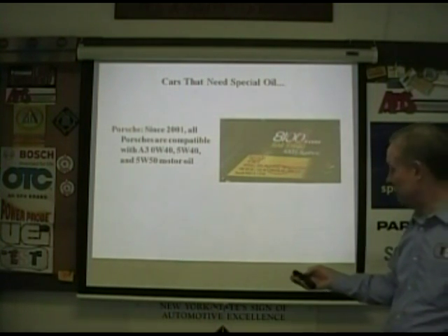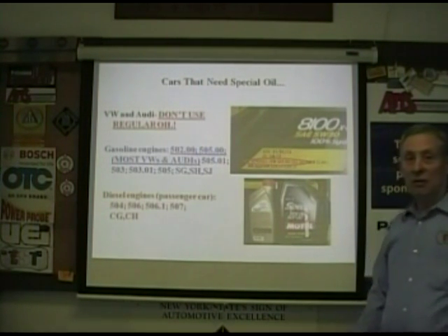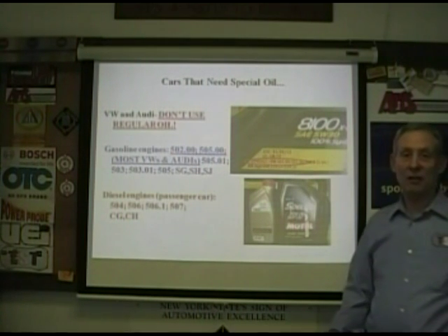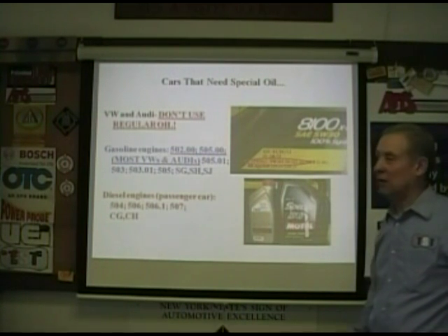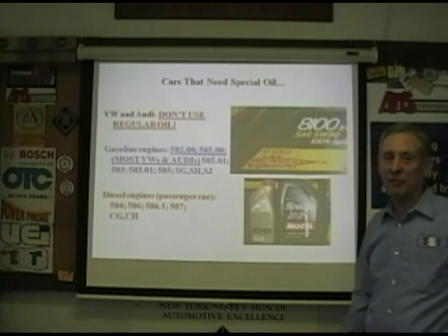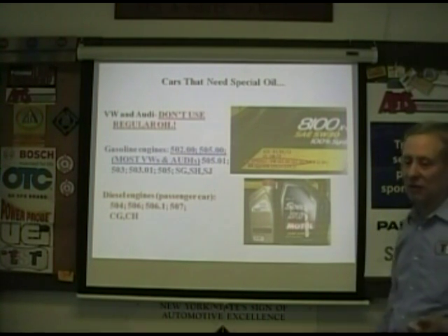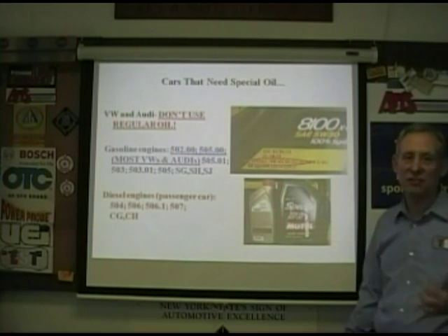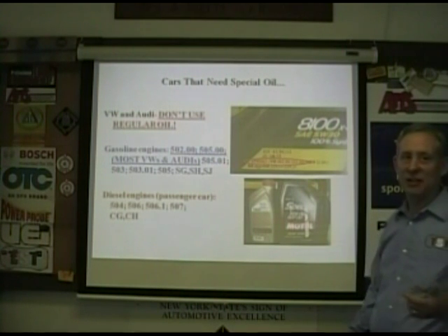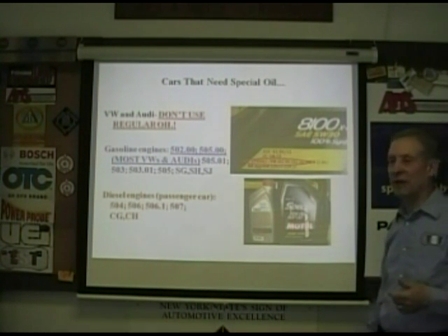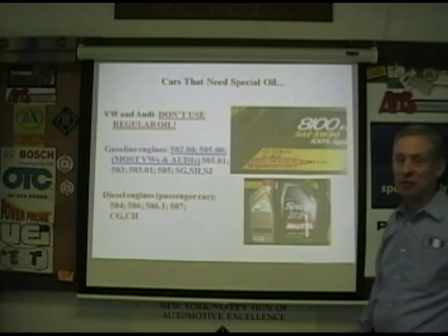ACEA is a European standard. So what may happen if I put the wrong oil in that Porsche? What are some common causes of putting the wrong oil in today's car? Common effects are some type of upper end damage, that's the most common thing. So cam distress, lifter distress, Vanos or whatever variable cam timing system is in it, distress. Eventually the metal gets into the bottom end and starts chewing up, if it punches through the oil filter, it gets into rod bearings. Usually it's top end distress.